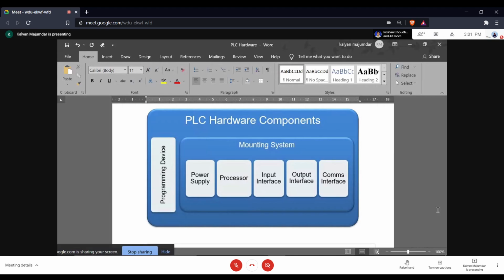In a PLC, okay, one hardware malfunctions. What you do is remove that hardware and replace it with similar hardware. So during this replacement duration, your PLC is not working, so your process is not working, your equipment is not working, your machine is not working. So in that case, what you do is you have two, three, multiple processors, multiple output interfaces, multiple interfaces. Everything can be replicated. Everything can be duplicated. Technically, you say that you're making it redundant. You're making hardware redundant. You're using multiple pieces of hardware to do the same job. The idea is if one piece of hardware fails, there's a second, identical piece of hardware which can take on that responsibility and continue with the job, so that you do not have system failure, you do not have equipment failure, you do not have process failure.